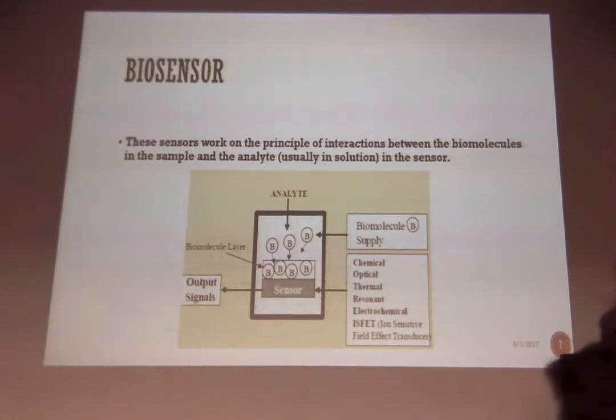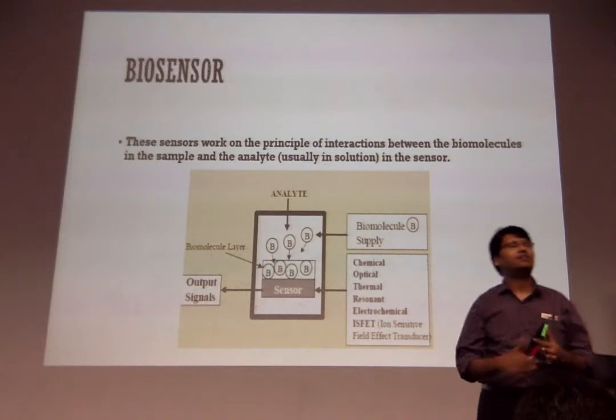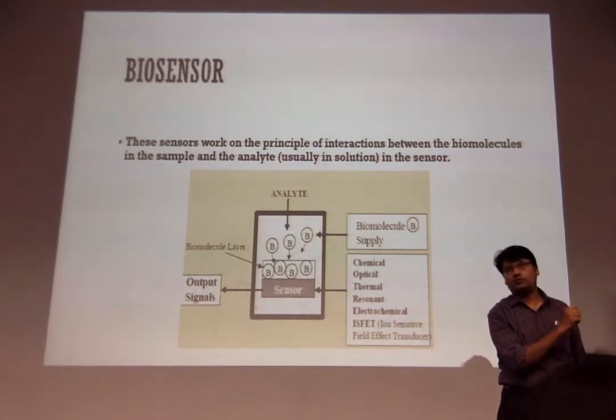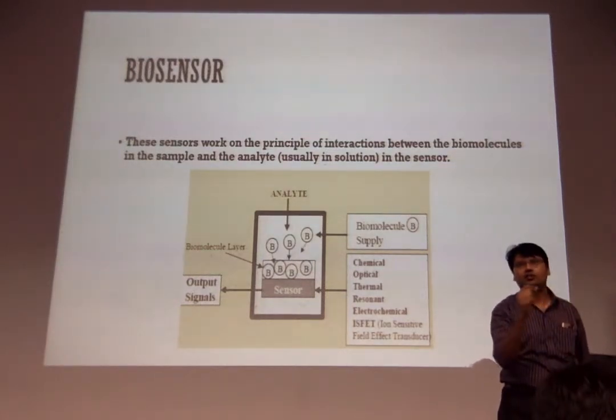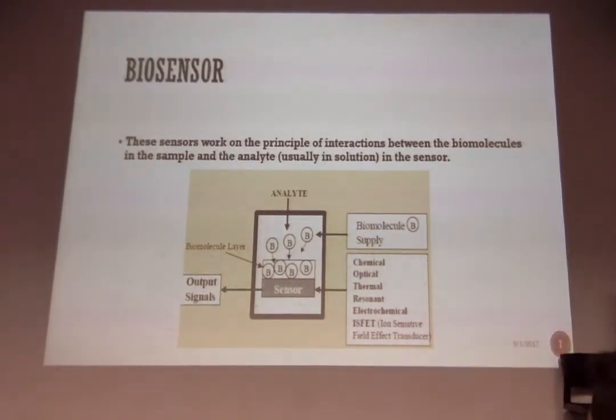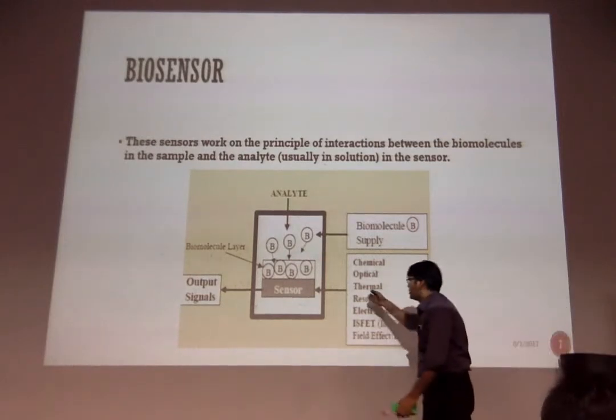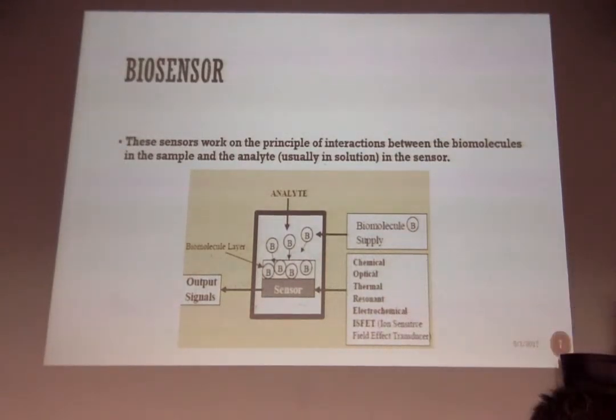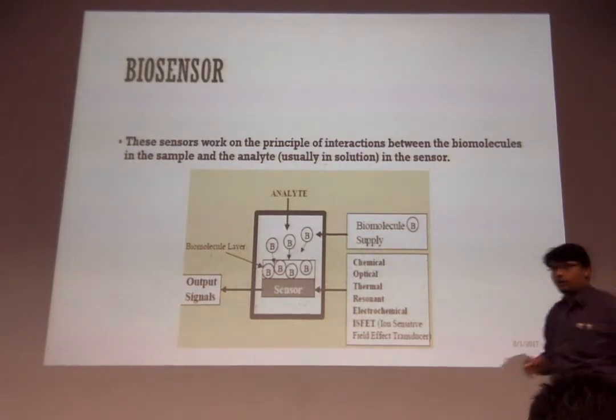These kinds of sensors we call interdigitated electrodes. Many manufacturing techniques can be adopted, and the simplest one is simple PCB fabrication. Now in biosensors, they take this kind of conductometric sensor and coat the sensing material, the biomolecule, on top of it.